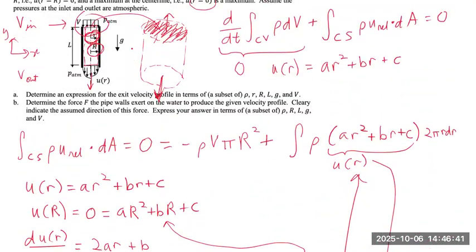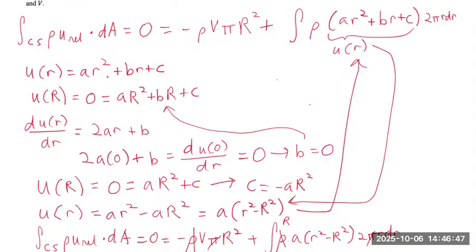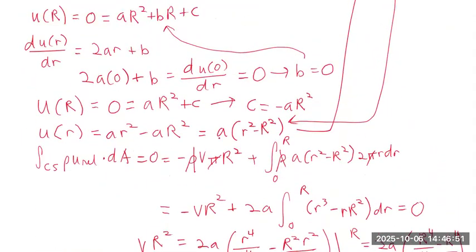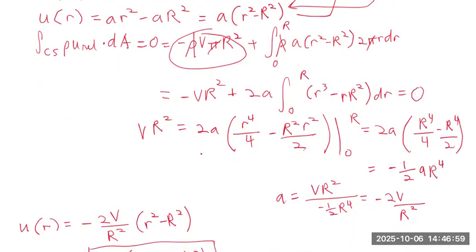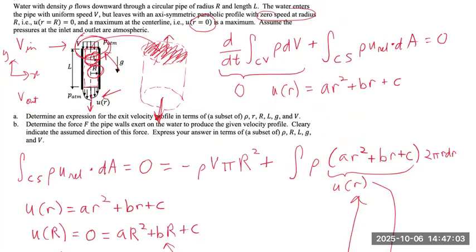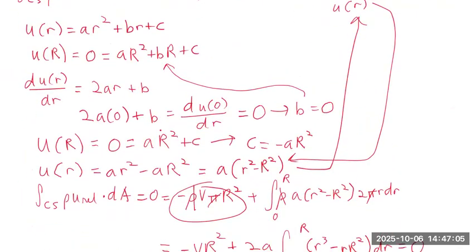We have one type of flow over here, and another type of flow down here. For the entry point, we found that it's equal to rho v times pi r squared. So now there's just going to be an additional v term since that is the velocity going in, and that velocity is pointing downwards.